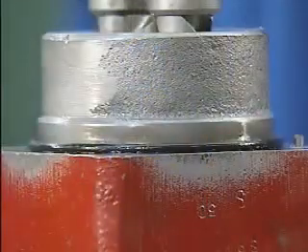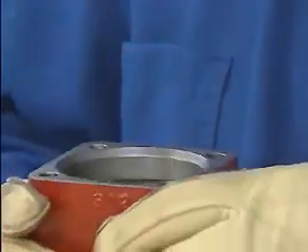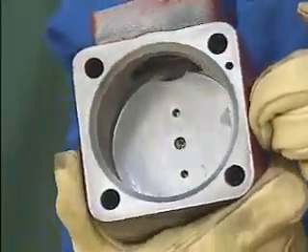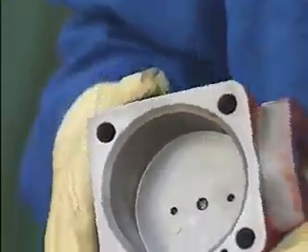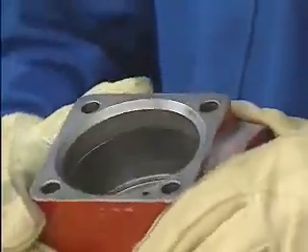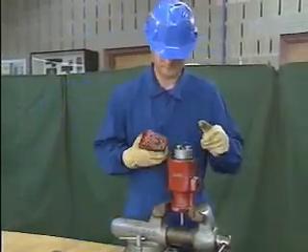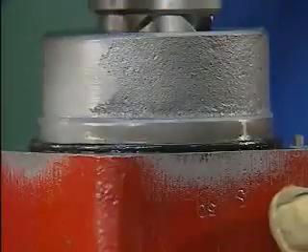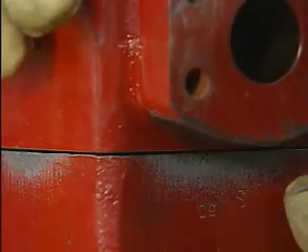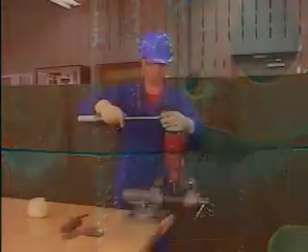Care should be taken during this step to make sure that the O-ring is not pinched. Like many O-ring applications, the opposing or mating flange has a special fit designed to help compress the O-ring into position. On this application, the mating flange has a beveled edge that contacts the O-ring when the two flanges are bolted together. The angle of this beveled edge compresses the O-ring evenly against the vertical surface of the sleeve and the horizontal face of the flange, forming a proper seal.